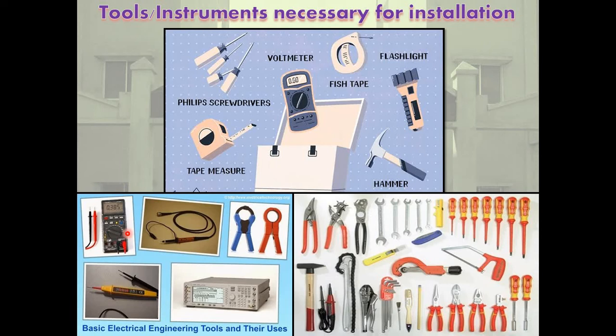Avoid water at all times when working with electricity. Never touch or try repairing any electrical equipment or circuits with wet hands. It increases the conductivity of electrical current. Never use equipment with damaged insulation or broken plugs. If you are repairing an electrical device, always turn off the main supply.